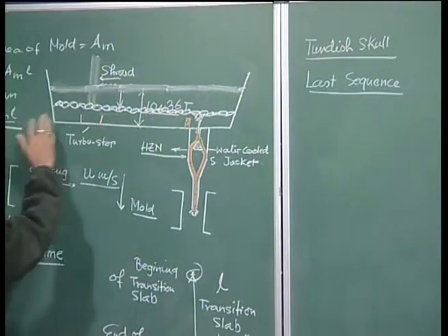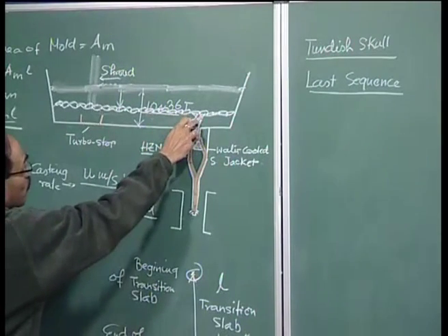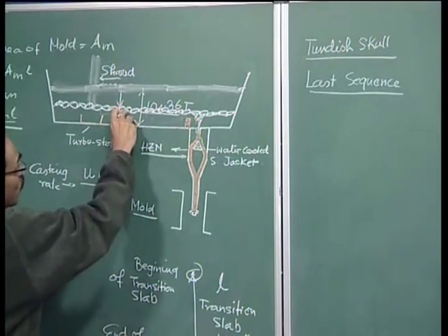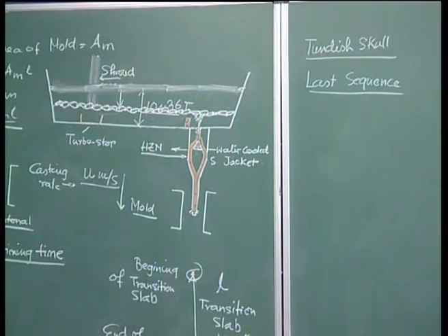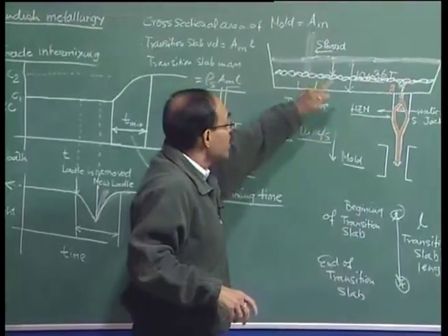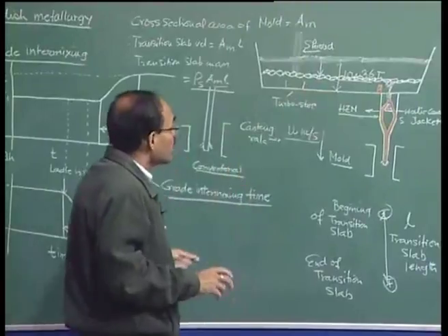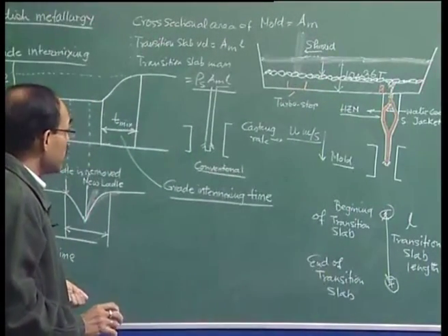So, the tundish geometry can be altered with suitable fundamental knowledge, and once you can alter that, you will have vortex formed in the tundish not when there is 7 tons of material, but when there may be just 2 or 3 tons of material. So, it is possible to salvage a reasonable proportion of the residual liquid by altering the design of the tundish and casting practice to some extent.